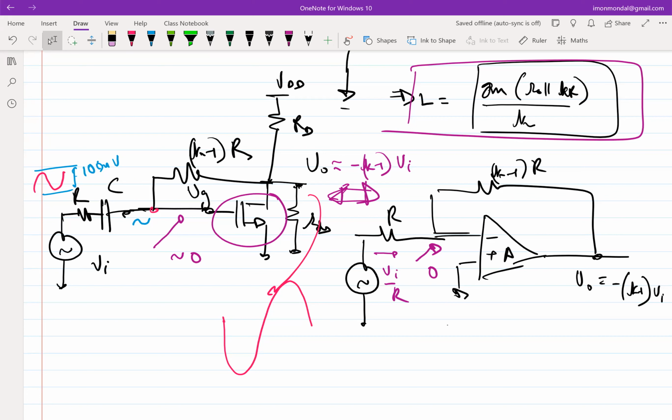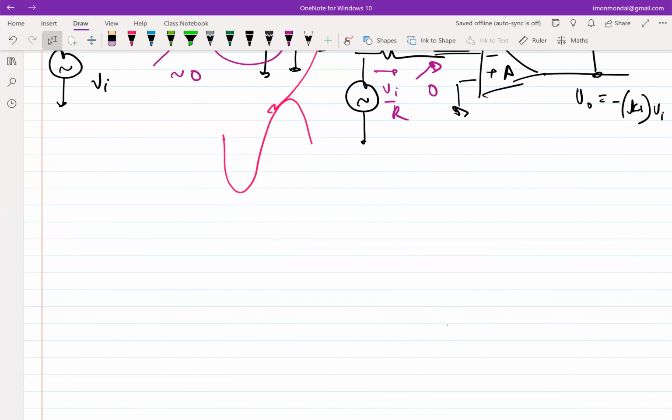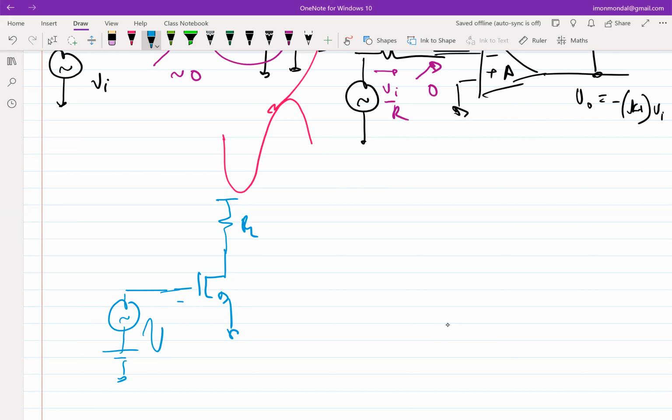Right? So negative feedback reduces nonlinearity in a nonlinear network as well. So in a common source amplifier, if you apply a 100 millivolt input directly, the 100 millivolt is applied directly across the VGS. Correct? So as I'm trying to allude to, let's say I can get an open loop gain of K minus 1 by setting the GM times RL to be K minus 1. Right? That I can do. But let's say I apply an input with a bias, and this goes like 100 millivolt peak to peak. This 100 millivolt peak to peak directly appears across VGS.